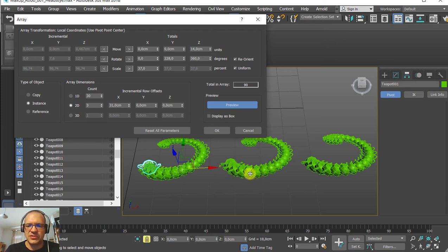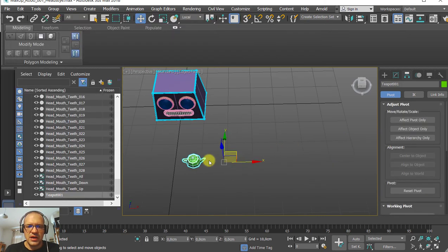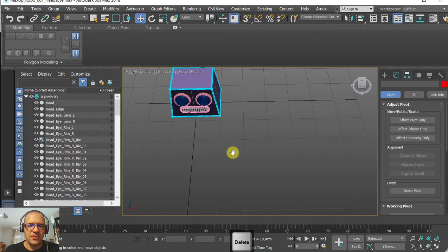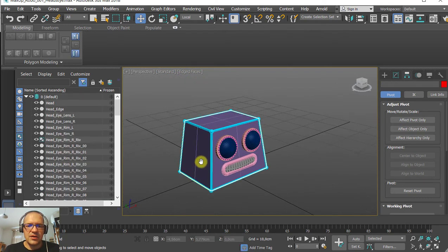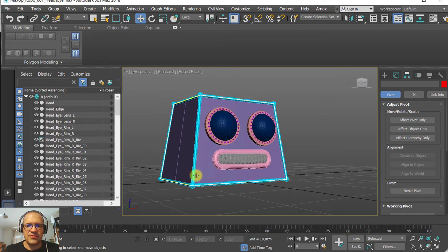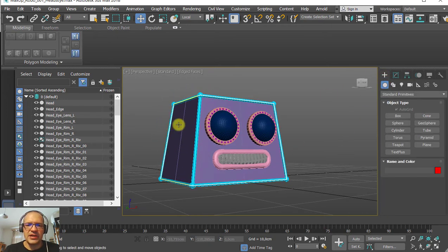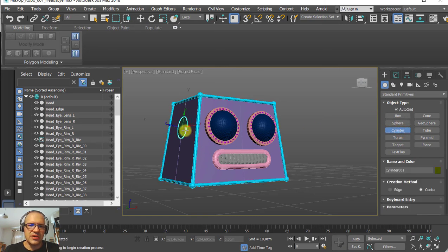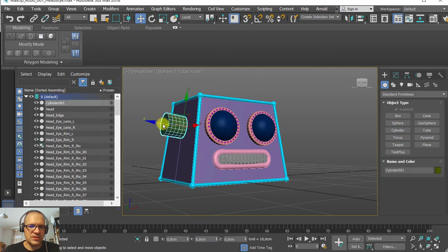Teapot is good because you see the orientation of the lid and the spout and everything. Alright, let me hit cancel. And let me delete the teapot. And so that's it for the basics. You can try yourself creating ears. Like you can go cylinder, one cylinder here, extrude, then choose shift. I'm in local mode, shift and drag it out.